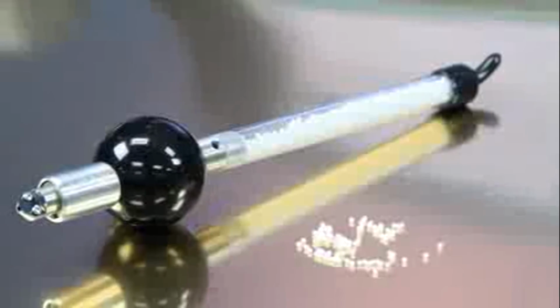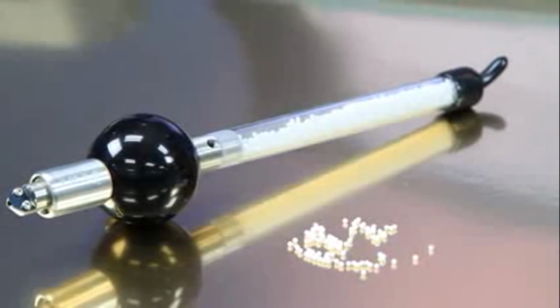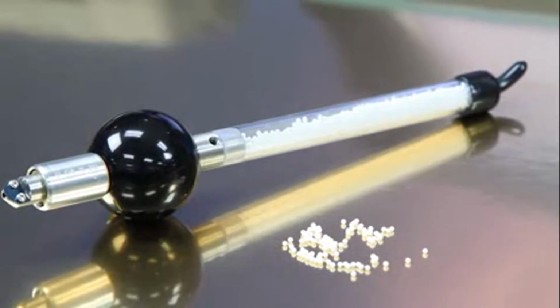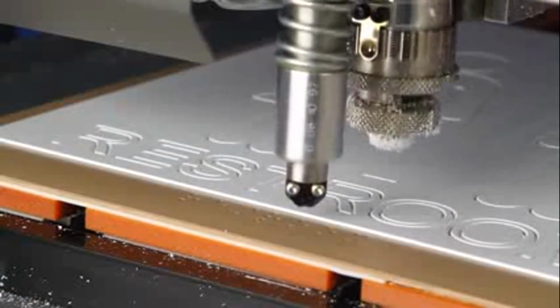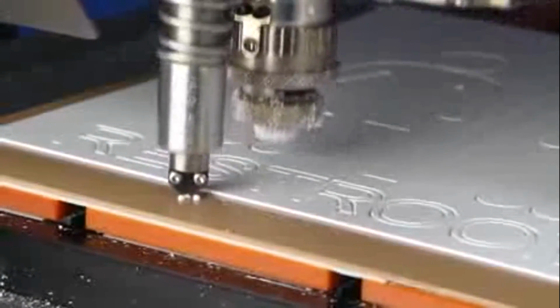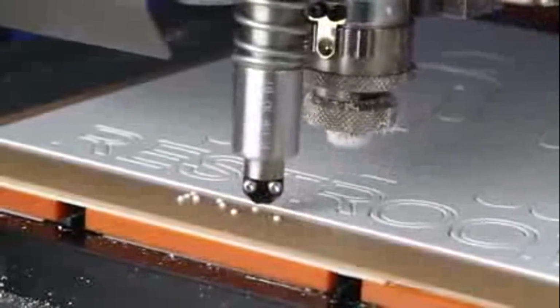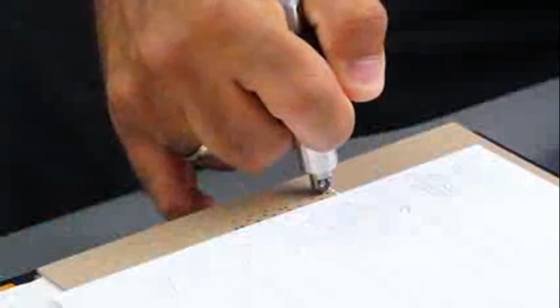To create the raised Braille text, you'll insert specially sized plastic beads called rasters into the holes you've just engraved. There are two methods of inserting these rasters. For the EGX 400 and 600, use the Auto Raster Insert. For devices without the Auto Raster Insert, we recommend using the Raster Pen tool from Accent Signage Systems.